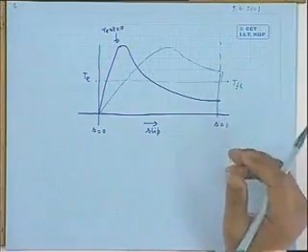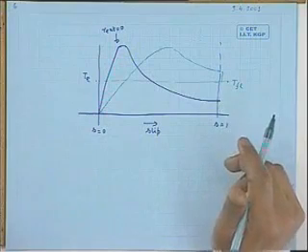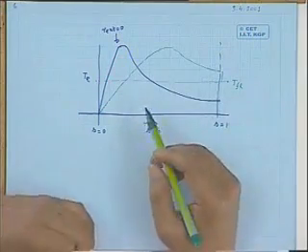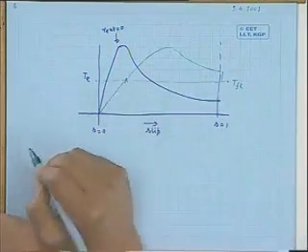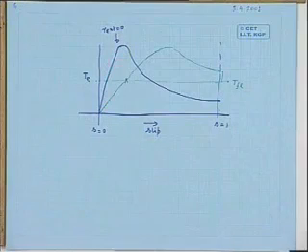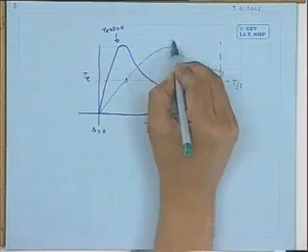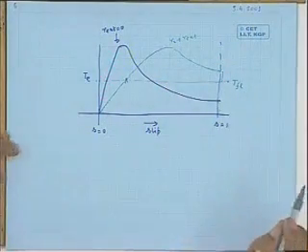Now the point is, suppose I keep that resistance in the circuit, I don't bother, the machine is started, fine. Where will the machine settle down? Which will be the operating point of the machine if you don't do anything with R external now? It will be here. Because this is the torque slip curve prevailing in the machine now, dictated by the present value of rotor resistance per phase, which I have increased and did not bother to cut out. It was there in the circuit. So this is, as I told you, R2 plus some R external.